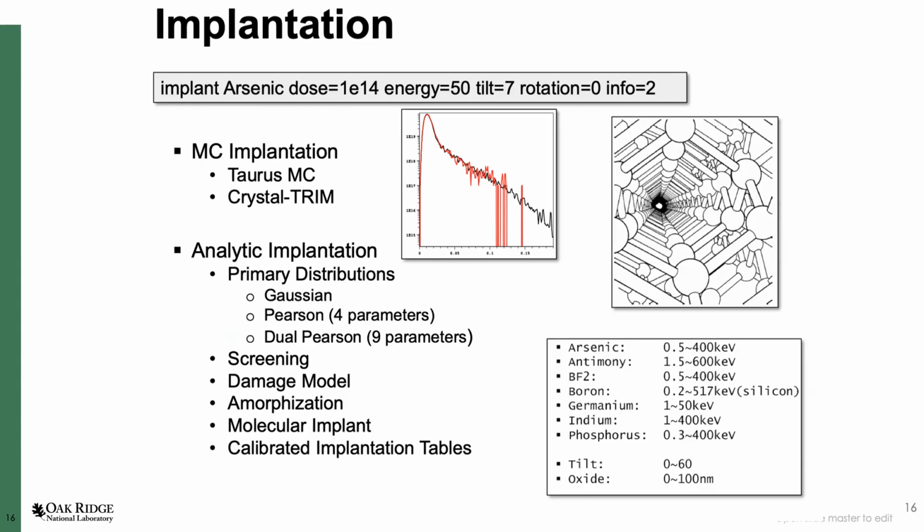It can calculate the damage introduced when you do implantation. It can calculate amorphization that occurs in a highly doped semiconductor when you do implantation. It can handle molecular implants, for example boron fluoride. And it has what we call calibrated implantation tables.